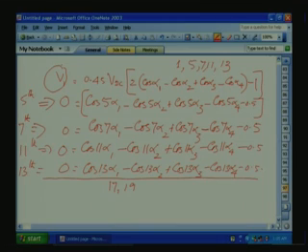Whenever we want to vary V1, just vary the modulating wave amplitude. So automatically the fundamental is generated. At the same time, harmonics are shifted to the high frequency side, which is proportional to our fC.